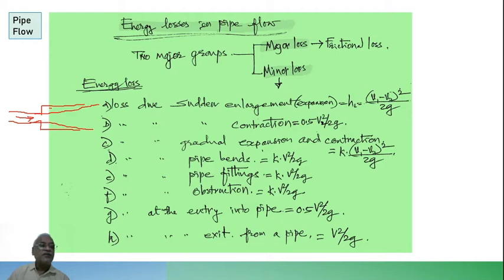So here there will be a stagnant liquid. Because of that there will be some energy loss, eddy formation we say. The flow gets mixed up like that and then it gets rotating over here and then stagnant there, but the flow will be continuous in this section. So because of that there will be some energy loss. That is what is called sudden enlargement.